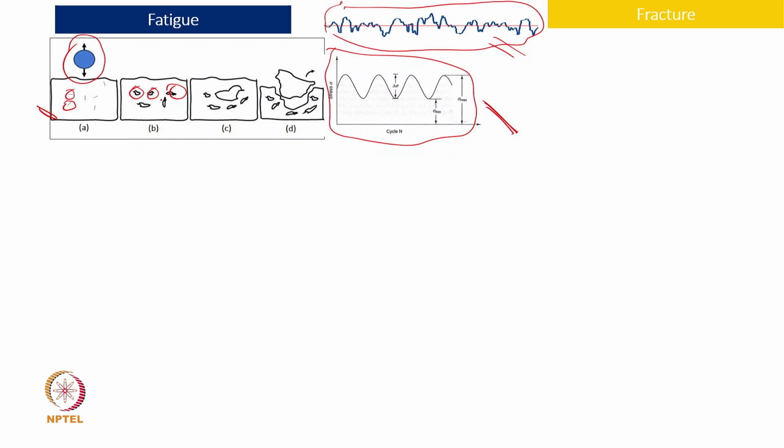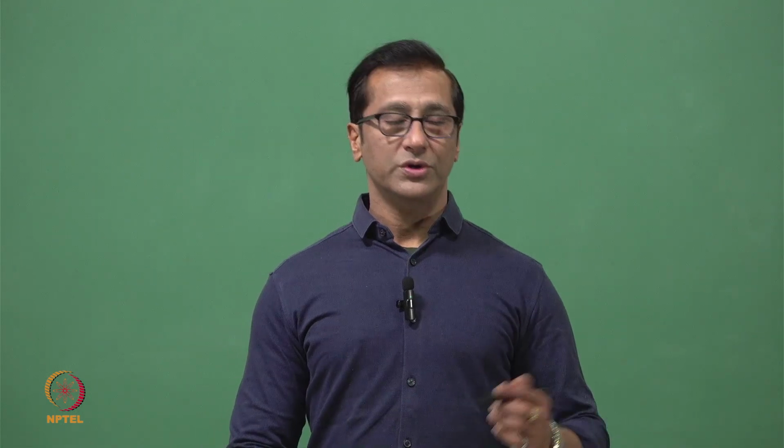Slowly, as they grow, quite possibly two or three cracks get merged together and become a big crack. Slowly it will move to the surface and a whole chunk will come out, and that is the wear debris. Even though it is shown larger here, this wear debris can be even 5 micron size, or the maximum size can be 5 micron. We will study this in lecture 18.